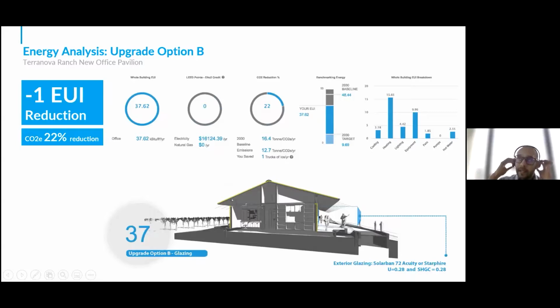This last graphic is basically telling you, is your building cooling dominated, or is it heating dominated, or lighting, or is it maybe plug loads dominated? And that basically tells you if you're getting a lot of heat. In this instance, it is saying this building is heating dominated. That means you have to provide a lot of additional heat, which also means you're actually losing a lot of heat, or there are a lot of exposed areas. If you have to provide a lot of cooling, that means there's a lot of heat gain happening, maybe from the internal gains, or maybe because you have larger windows, there's a lot of sun coming in. So there's not just one simple metric that can define that. You will have to see a combination of the different outputs to understand exactly what's going on with the building.